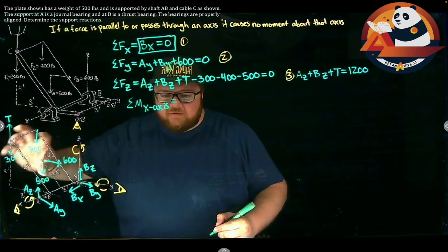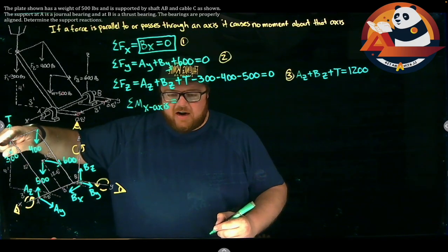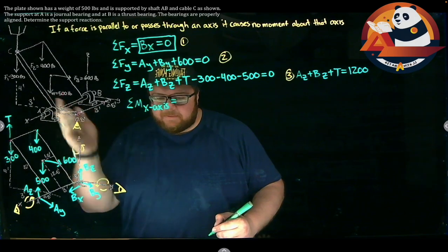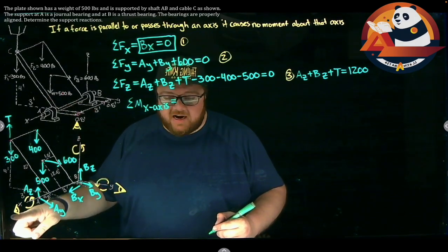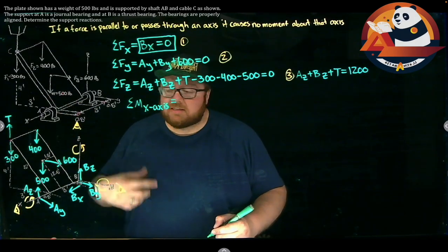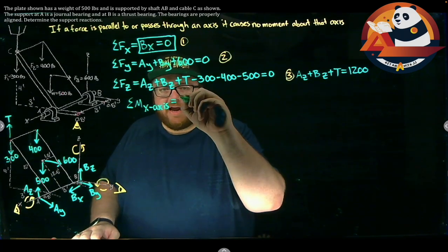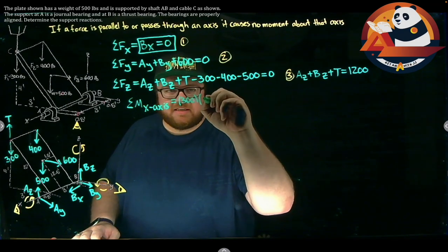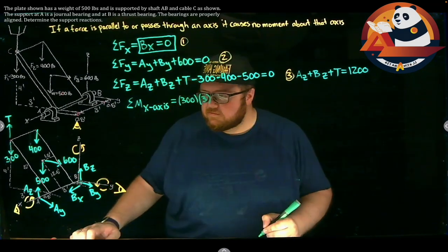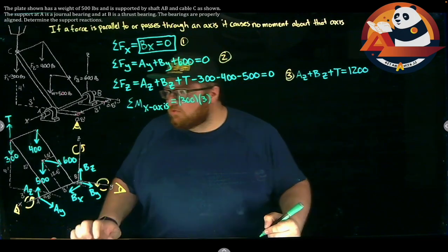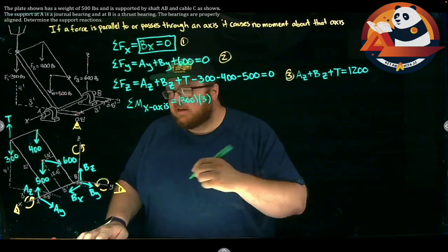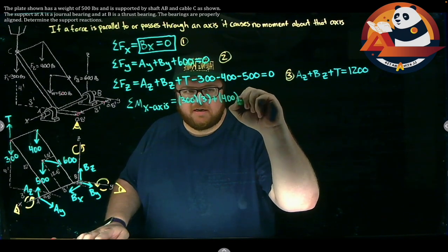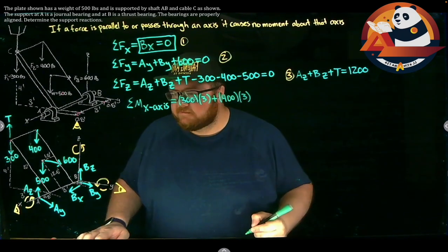If we could only rotate about the x-axis, and all that I did was pull down on the back corner of this, we would swing down under the x, up and around. It would look like we were standing right here, like it's going counterclockwise. So this is positive for us. My F1 is 300. Force times distance, 3. We'll get F2 in here, would also be positive. It's also 3 feet away. So plus force 400 times distance 3.